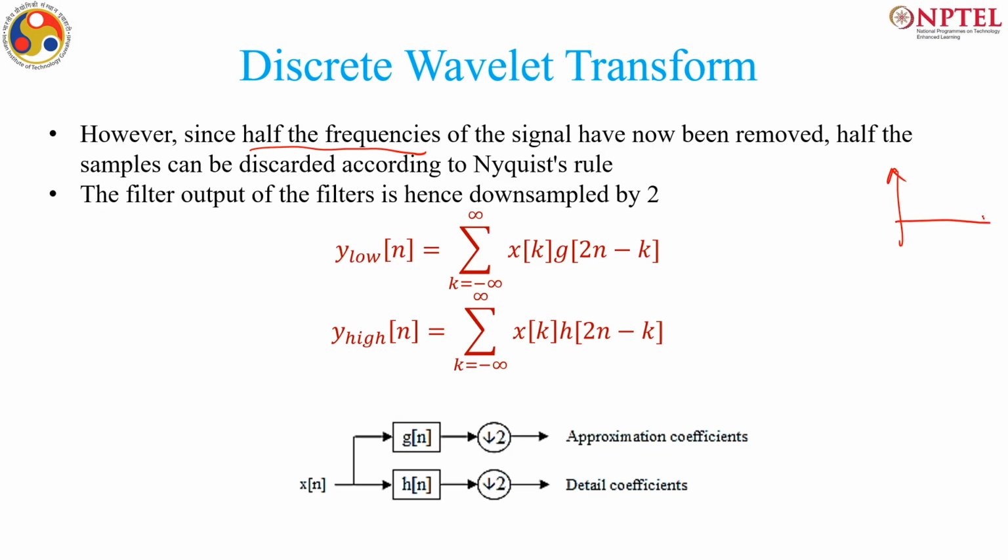So if I say 0 to pi, this is the frequency content of the signal. See, it may not be like this, there can be high frequencies lot present as well, but let me take a different color. So, say this is the region. If it is an ideal filter, it would take up only this region. This is my low frequency part, but real filters will somehow have a smoother response.